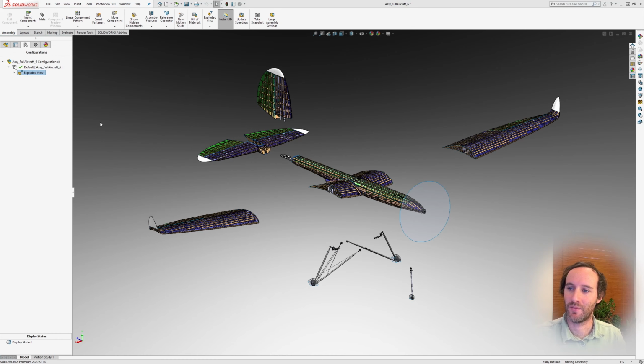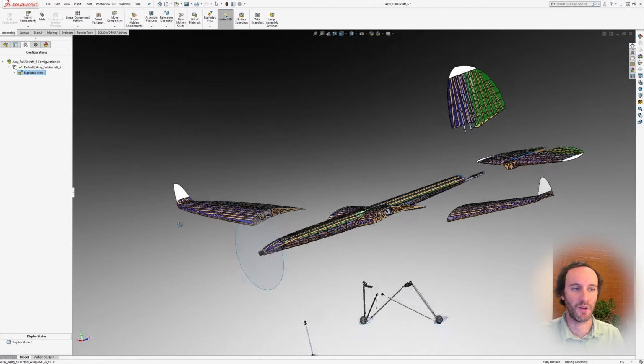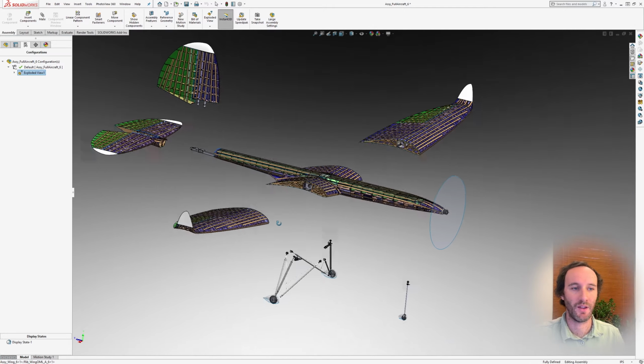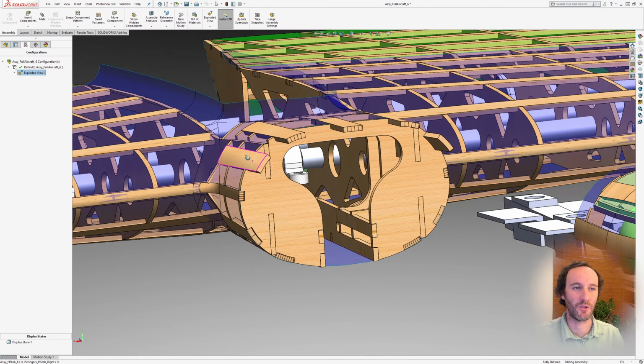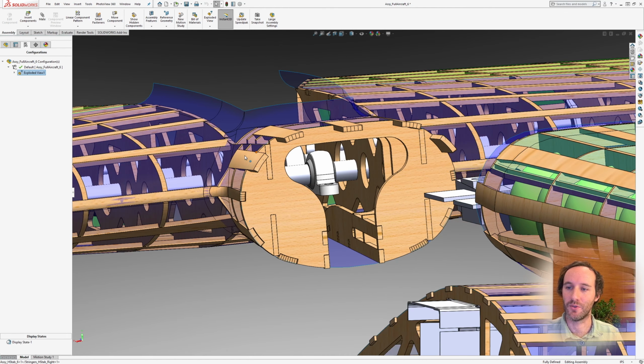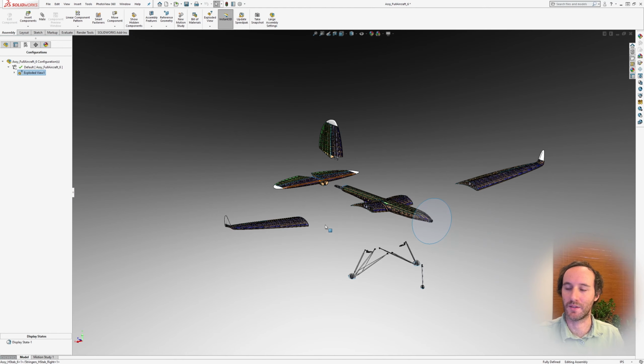So in summary, if a design calls for long structural elements that bend and twist along a surface, and we want them to only bend in their minimally stiff axis, then the wrap feature can accomplish all of this with an efficient and elegant design flow and feature manager tree. If the curvature is tight along the thinner direction, then we can use the Euclidean surface offset and lofts from the split lines.